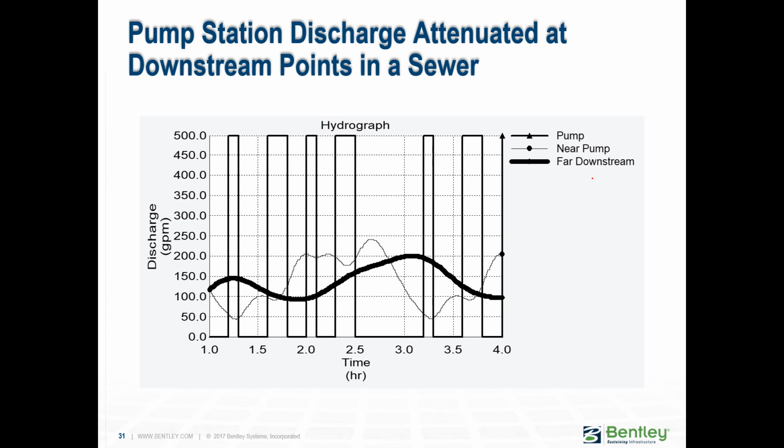Okay, and why do we have that option? Well, because if you look right at the arriving end of the pumped flows, you're going to see something like this. You're going to see the discharge being like, there's no water, there's no water. Pumped flows, and then no more flows. The pump is on, flows, pump is off, pump is on. So you see that right near the pump.